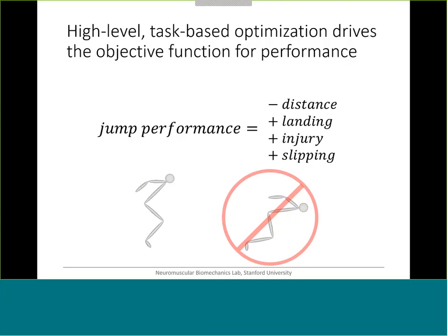We penalize the jump if it was likely to slip during takeoff, since contact is modeled by point constraints. This is done by ensuring that the ratio of the horizontal ground reaction force to vertical ground reaction force is below a threshold. This is most relevant right before takeoff, and the model on the right would likely be penalized as it would probably slip if it were to take off in that configuration.